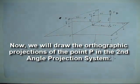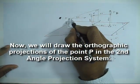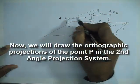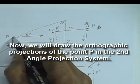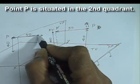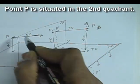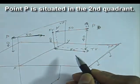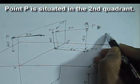Now we will draw the orthographic projections of the point P in the second angle projection system. So the point P is in the second quadrant, and it is 50 mm behind the vertical plane and 40 mm above the horizontal plane.